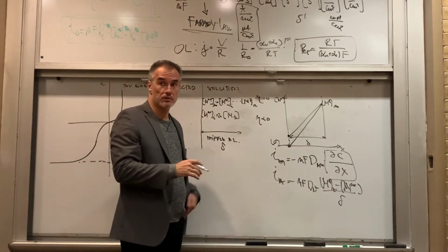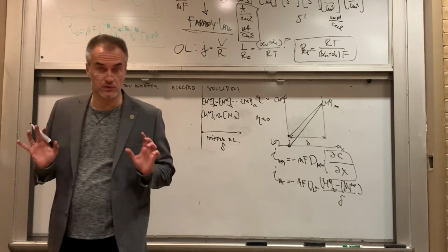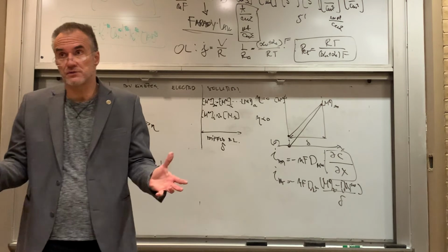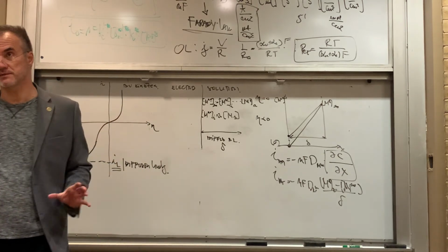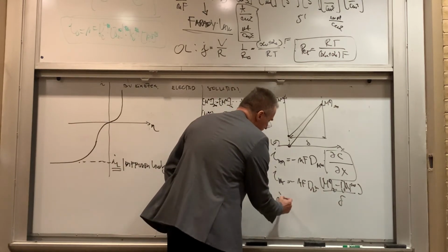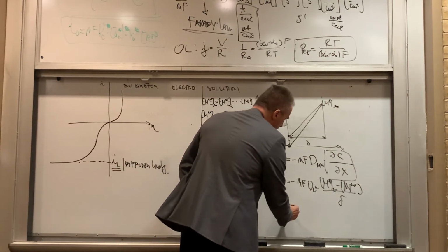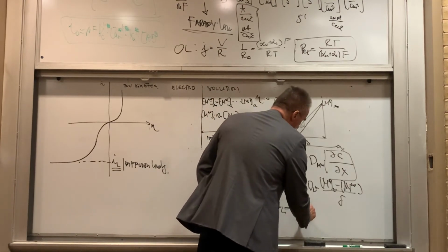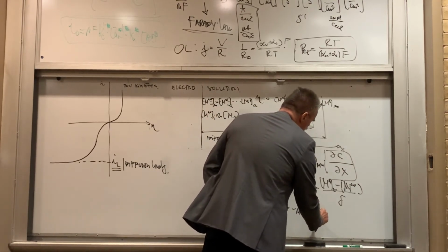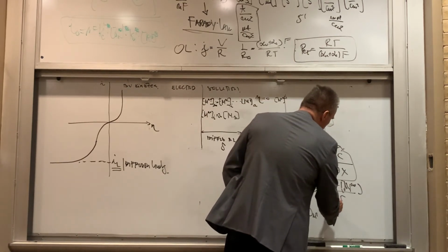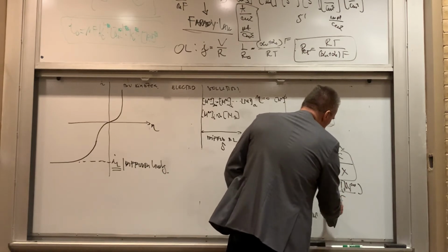That will correspond to the maximum current that the transport through the boundary layer can conduct, regardless of how fast the kinetics you have. It cannot supply more ions, right? So this means that we have a limiting current density, which is based on the diffusion limitations. I'm going to call this I_L equals n F D (metal ions), by the way, this is diffusivity from Fick's law, and then this is the bulk concentration over delta, okay?